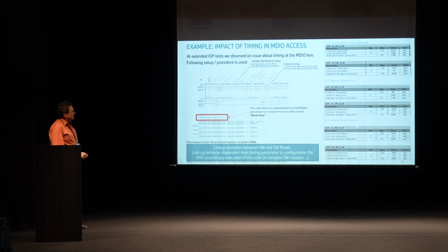And it goes to the link-up time which we can achieve with a hardware reset if we wait for 60 milliseconds, 40 milliseconds. So we find out why we potentially observed different link-up timings before, and it depends on the timing parameter. Nowhere is it written that it's this case. And nobody can guarantee that you can have a variable link-up time or not in a complex system. If you think of a Linux stack, it might take 2 milliseconds, it might take 40 milliseconds. You get undefined behavior by the software parameters.